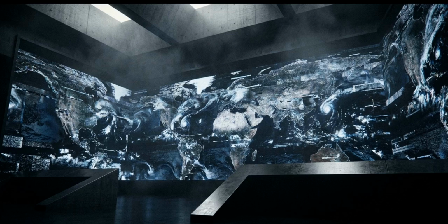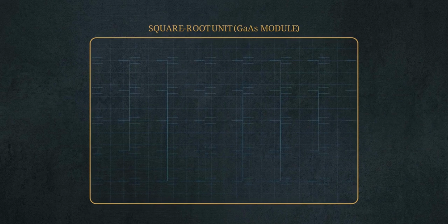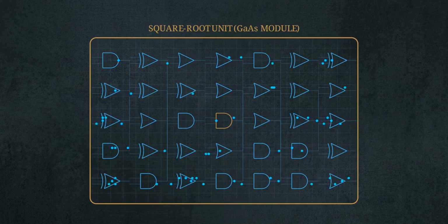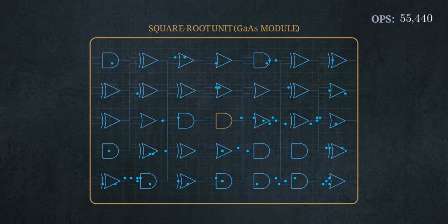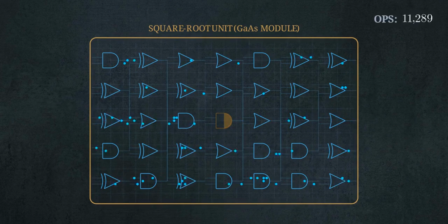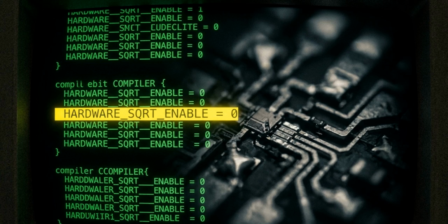The errors in the NCAR climate models originated from the physical fragility of the exotic hardware. The code was merely the mechanism that uncovered the buried hardware flaw. The defect was baked into the sub-micron logic gates responsible for the machine's new square root instructions. The corruption was microscopic and intermittent, occurring in exactly 1 out of every 64,000 mathematical operations. Engineers eventually patched the error by rewriting the system's compilers. They commanded the supercomputer to ignore its own square root hardware and default to slower, software-based approximations.